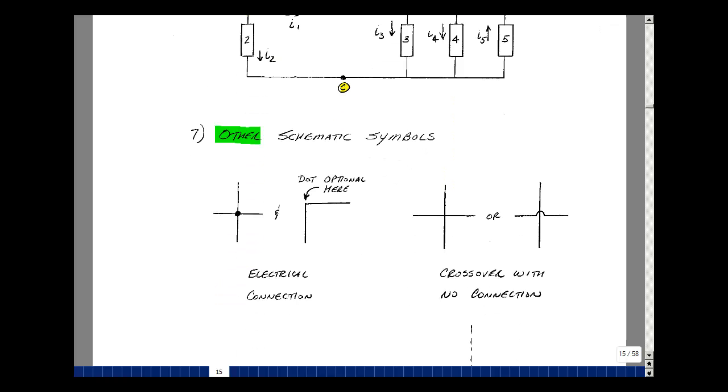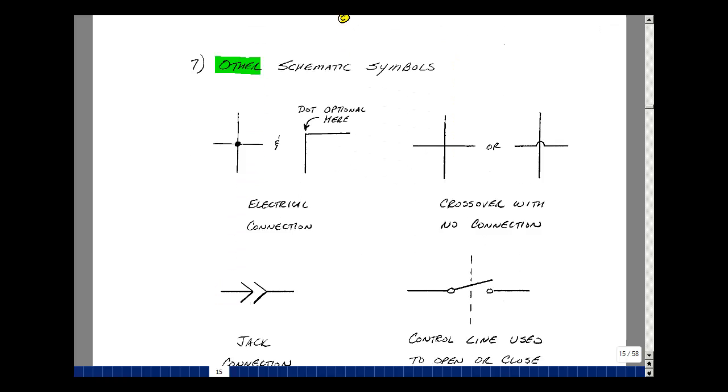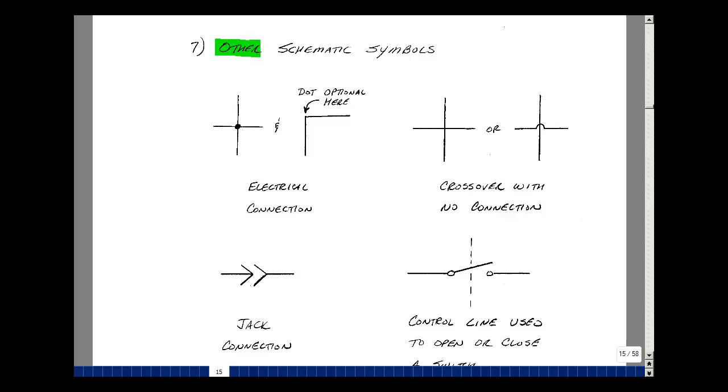There are other schematic symbols throughout the notes and in our textbook also. Let's explain these real quickly. Two wires cross and they're connected. We put a dot to indicate that they are soldered together or connected together. And of course here they're not. We can also emphasize this even more by showing a little jump over the wire. Now if you don't have a very large schematic, this is not hard to do. But if you have thousands and thousands of wires, then just this notation is a lot simpler. I'll do mostly this in the course to just double emphasize that we're not connecting at that point.